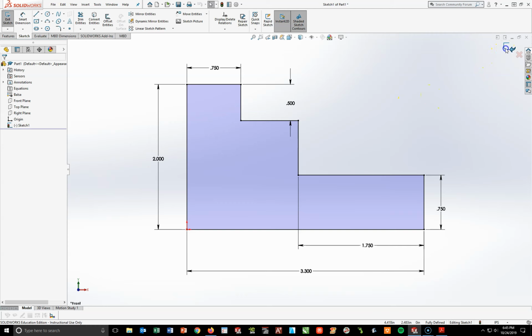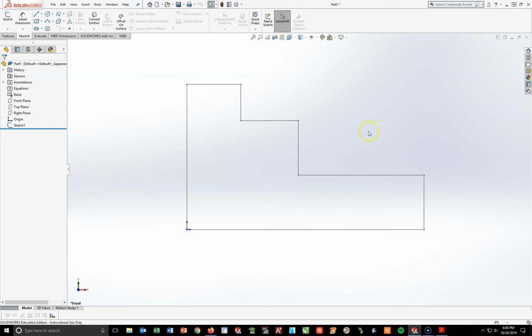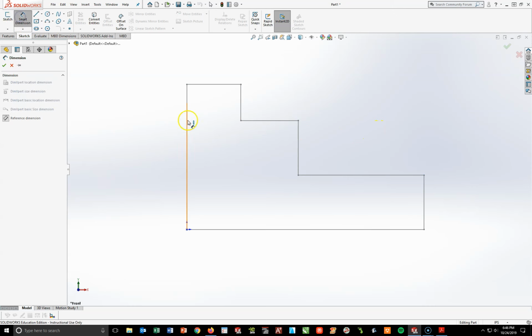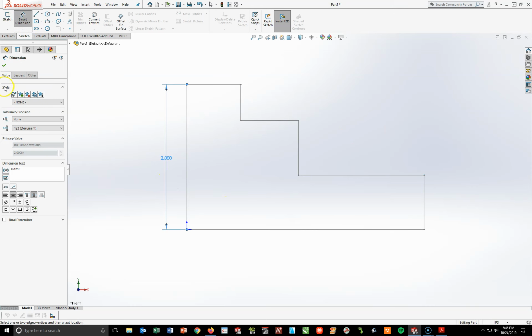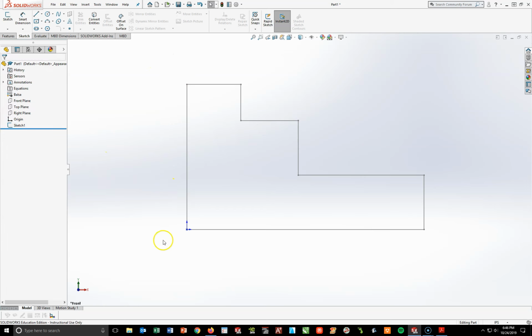And what I mean is suddenly the sketch goes gray on them. They go to start putting dimensions on and nothing's working. You're trying to change it, you keep clicking on it, nothing's happening. The reason they can't be dimensioned is because you've turned the sketch off. Okay, there's nothing going on.